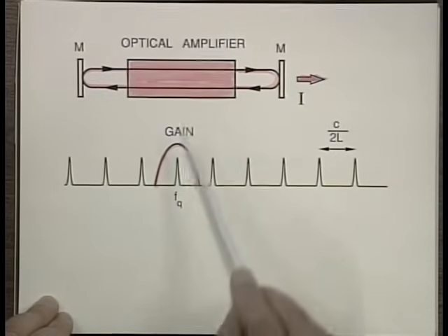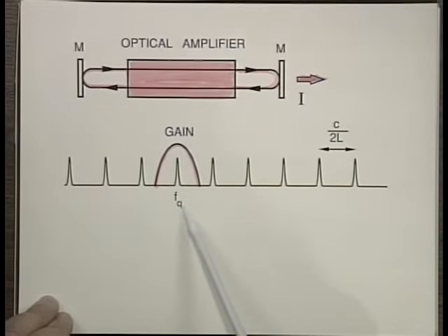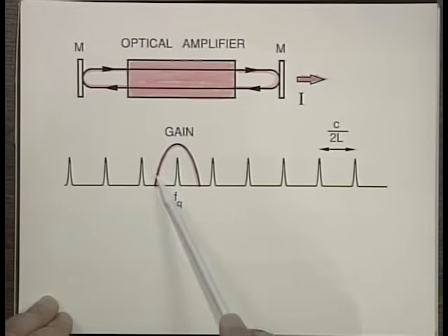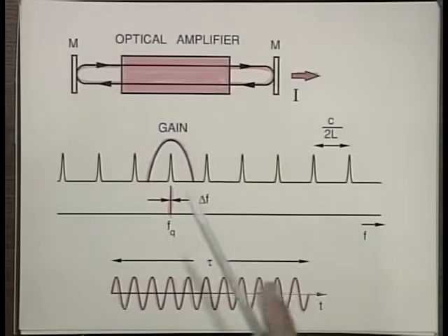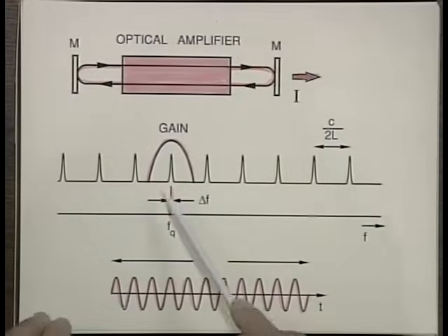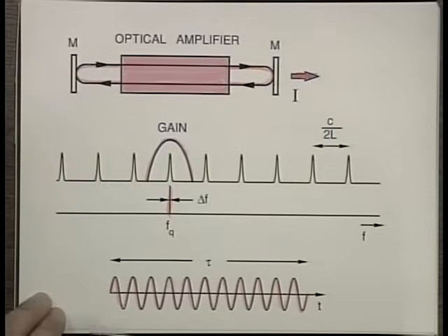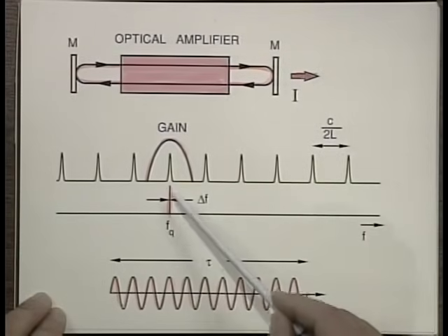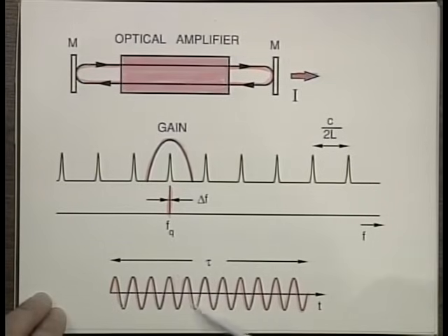And here, for example, I have the gain of this amplifier located at this particular frequency. And over here, I have all the modes of the cavity that we talked about before. But if there is one of these cavity modes under the bandwidth of this amplifier, and there is enough gain to overcome the loss, then I can get this to oscillate. And in fact, here it is. As we know, the width of the cavity comes about because of the losses in the cavity. But if I have enough gain to overcome the losses, then I collapse this width to the delta function that we had before. And the output that comes out from this mirror, if I put some transmission in this mirror and leak a little bit of light out, will have this very narrow spectral width, or in terms of the time domain, this lovely oscillation that has a constant frequency determined by this cavity mode and a constant amplitude.